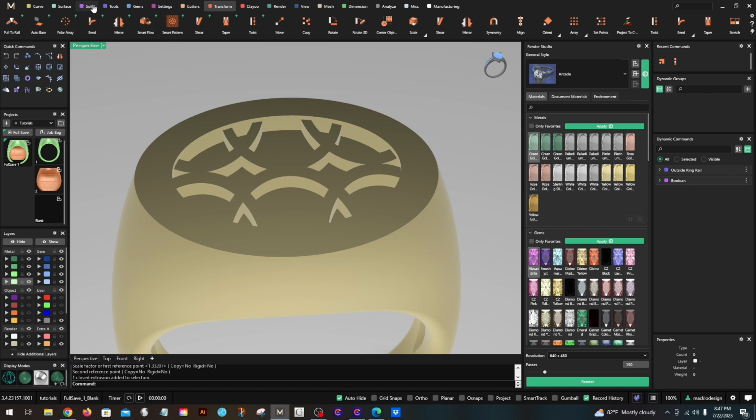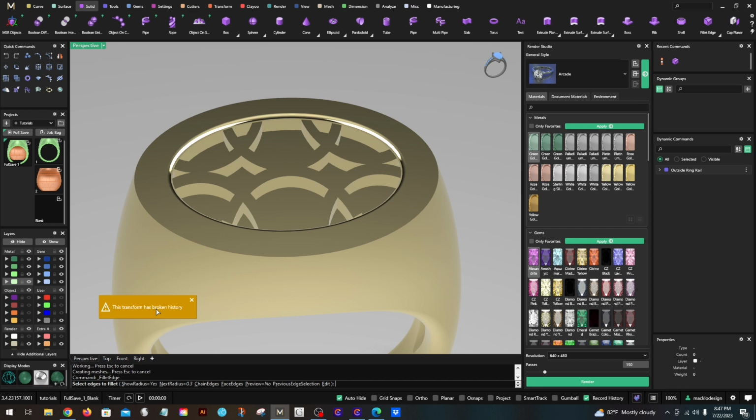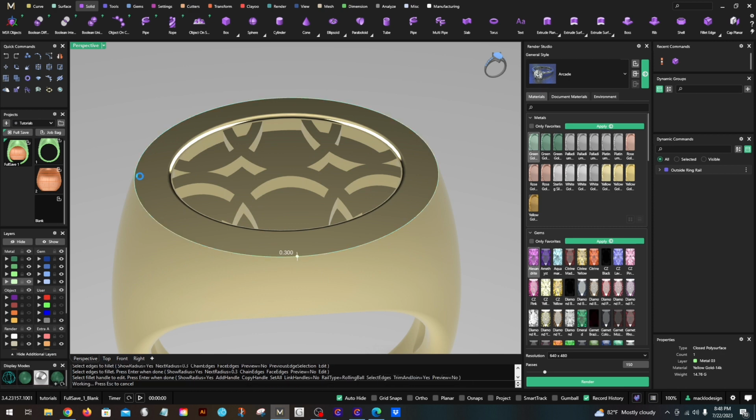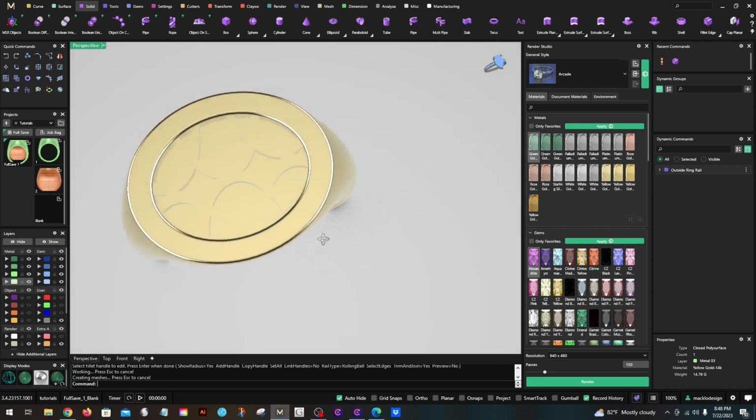So I fillet my edges and soften them all the time. So you go to fillet, and I'll do 0.3 here. Yes, thank you. All right, and 0.3 here. Let's go ahead and do the same. And you can see the difference. See what a difference that makes?